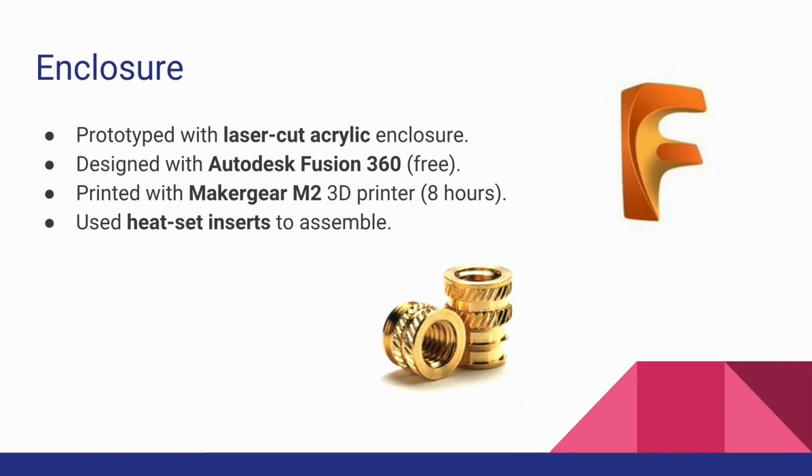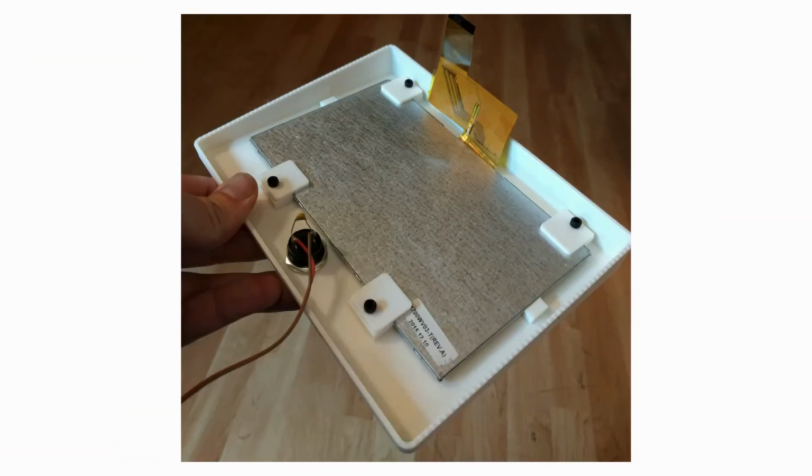And you can see them when I open this one. This is sort of halfway through building this. You can see the LCDs being trapped in by these 4 clips. And again, I used the heat set inserts there to hold that. And here's the button. This red button is just like the home button on an iPhone. When you go into demo, you can click it just to go back out to the menu. That's the only thing it's used for. And you can see the capacitor there for debouncing.